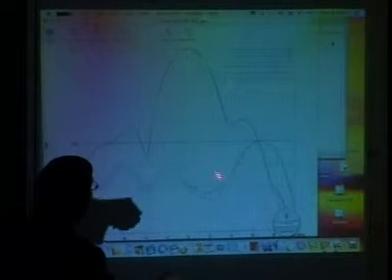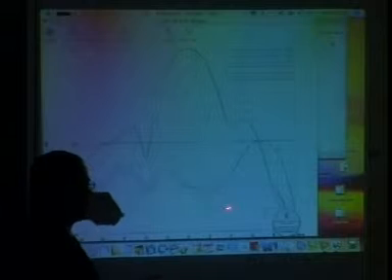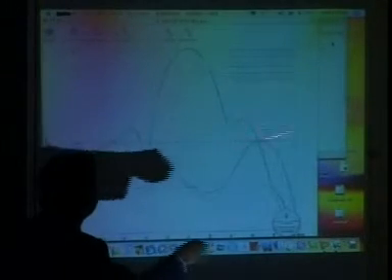The cross polar, at this main area of interest, is all way better than 30 dB. In some cases, it's even 40 dB. So this is the area of interest for us. These areas are not of interest because they will go completely out of range. When you are talking from the Moon, from Chandrayaan, to here, these areas are not of interest. Only this will be of interest to us, coming directly. And on this side, even the cross pole is very good. This is the plot for one plane, and this is the plot in the other plane. You can see it is nearly very symmetric.